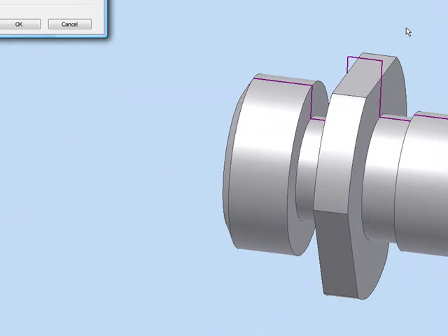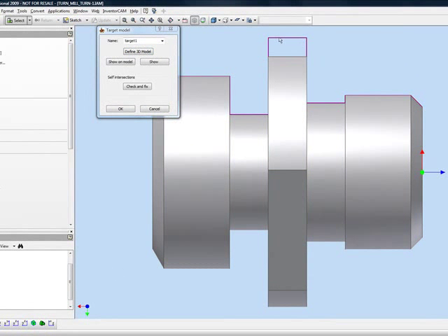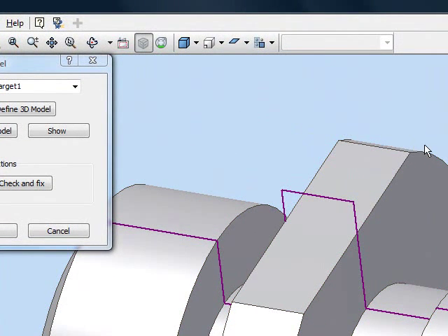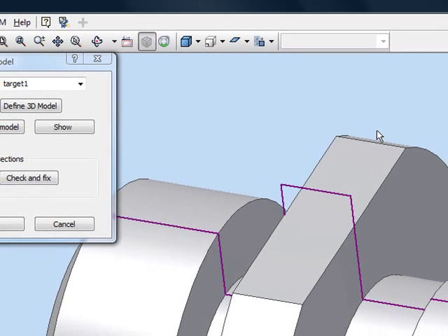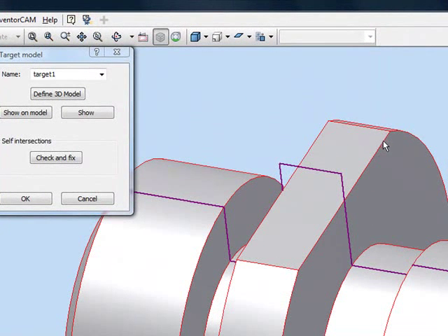Now, you'll note that the sketch that was created is not exactly on the part itself as we see here, but rather above the part. Again, this is because the part actually has to be turned, and this area is actually higher than this flat area itself. So the envelope is automatically taking into account the entire height of that particular area without having the problem of machining a part, turning the part, and going past that boundary. This is automatically taken into account with the envelope itself.